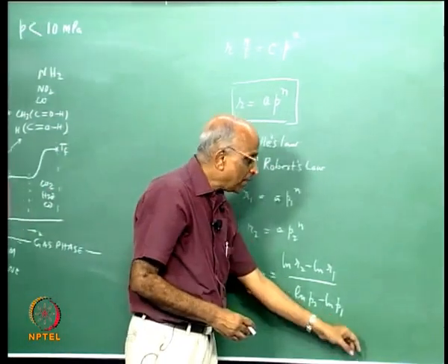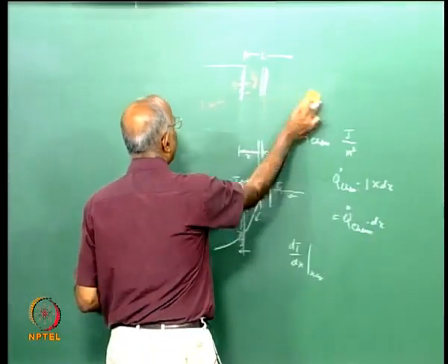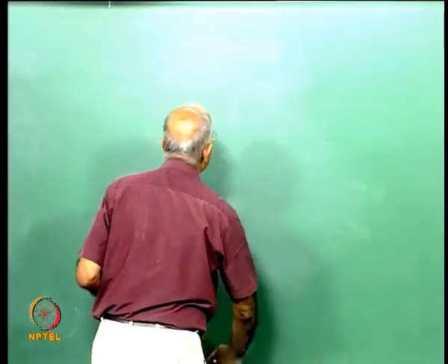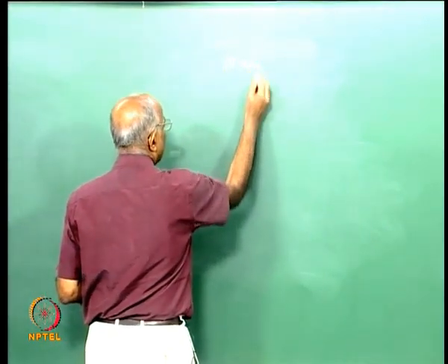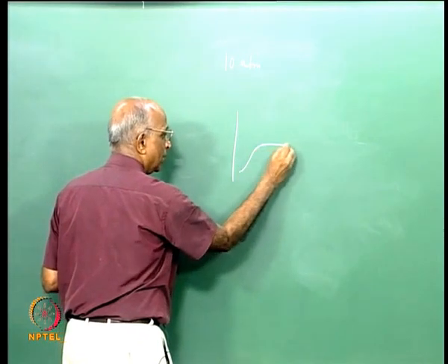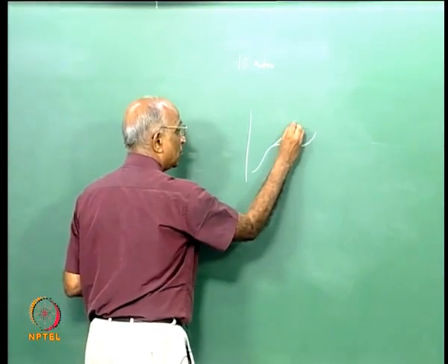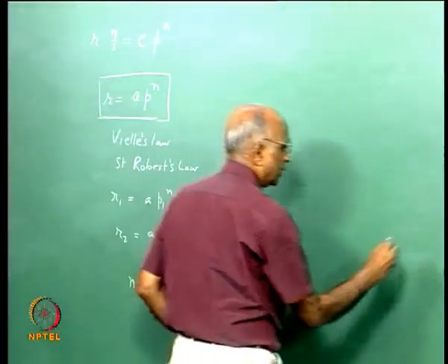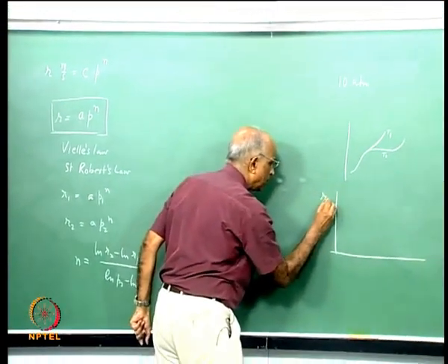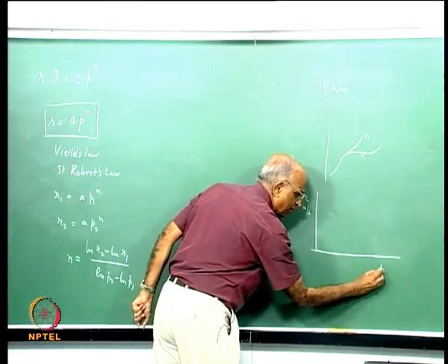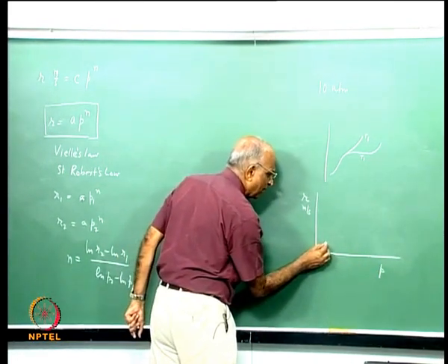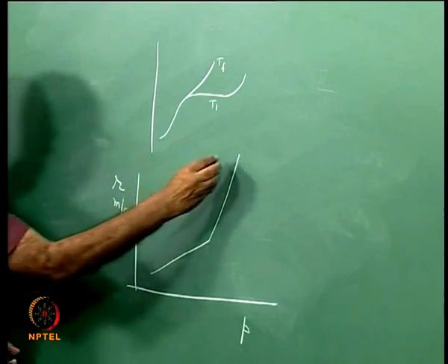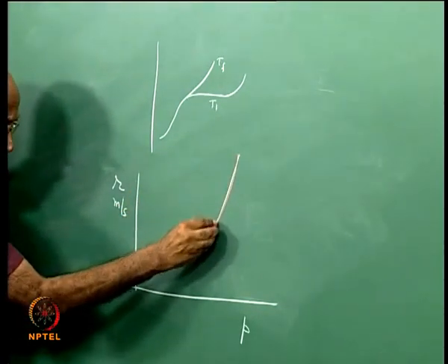This is how we determine it, but if the pressure is higher, in other words, if I have the ambient pressure in excess of, let us say, 10 MPa, then we told ourselves, well, there is no such thing as an intermediate T1 zone, it directly goes to something like Tf over here, more heat is conducted, and therefore, if I were to plot the burn rate r, let us say in meters per second, as a function of pressure, at low pressures I have n which is something like this, when pressure goes up it goes like this, or rather the curve will not be very marked like this, maybe the curve will be something like this.